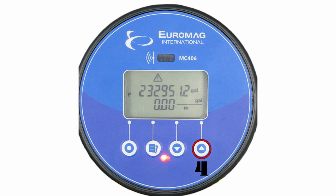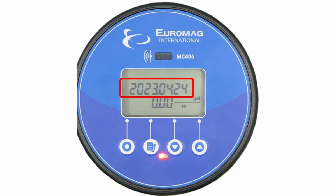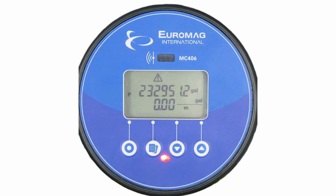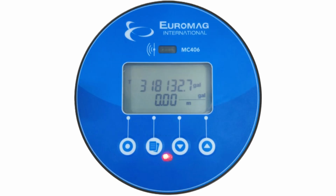Pressing the 4th button for a third time will cycle the P to AP negative, which is the partial reversed flow. The final screen visible when pressing the 4th button will display the current date. In summary, pressing the 4th button 5 times will cycle through the totalizers and reverse flow totalizers followed by the current date. The next section we will cover is accessing the function menus.